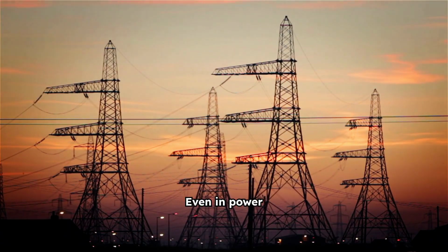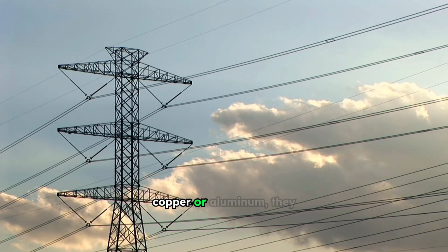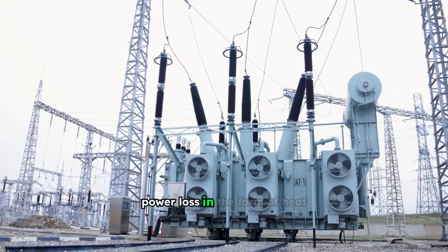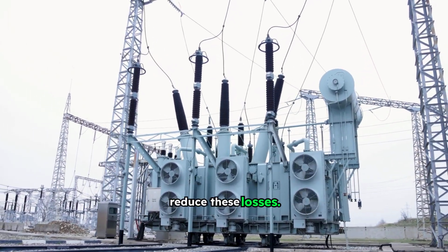Even in power transmission, resistance plays a role. While transmission lines are made of highly conductive materials like copper or aluminum, they still possess some resistance due to their immense length. This resistance leads to power loss in the form of heat during transmission, which is why high voltages are used to minimize current and thus reduce these losses.